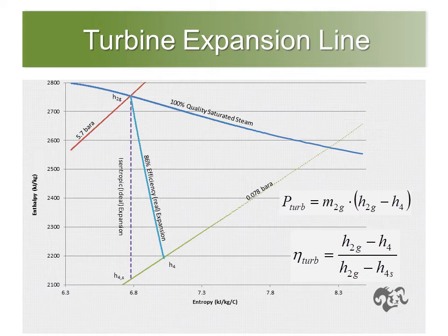There's actually a pressure drop between the separator and the turbine steam chest due to frictional losses in the piping and stop and governor valves. If you assume an adiabatic pressure drop, one with no work or heat transfer, then you move a bit horizontally from H2G into the superheat region. This reduces your potential enthalpy drop due to the upward slope of the enthalpy at the turbine's exhaust pressure.